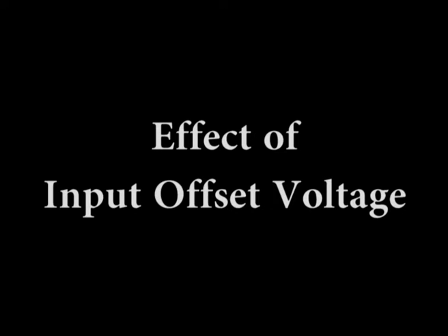Effect of input offset voltage. The output voltage of an op amp should be 0 when the differential input is 0. However, there is always a small output error voltage present whose value typically ranges from microvolts to millivolts. This is due to unavoidable imbalances within the internal op amp transistors aside from the bias currents previously discussed.